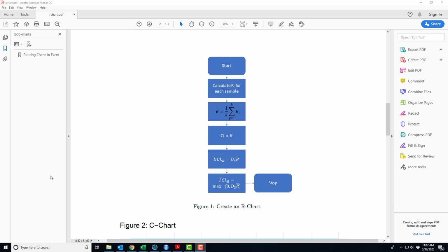With every control chart, at least with the C charts, or I'm sorry, the mean charts, I need to construct a range chart, and here's the reason why. Those mean charts, every time I take an average, it smooths out the data, so it's kind of like it's hiding problems. The R chart is just a second look, and the R chart is going to look at the variation in each of my samples, and I want the variation to be within a certain bandwidth, upper control limit, lower control limit, in order for me to claim that the variation in my process is not out of control.